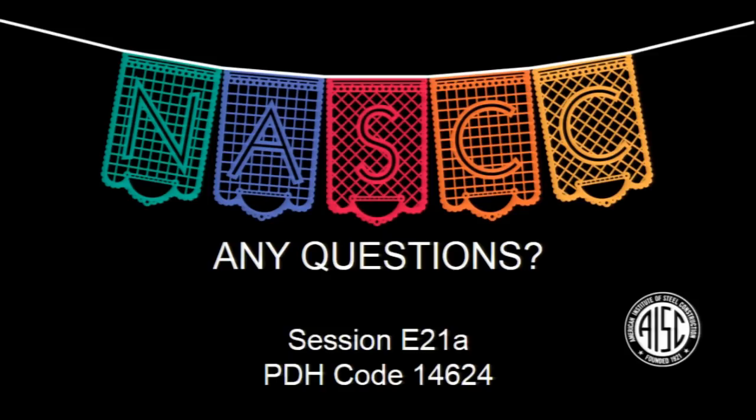First, you're going to start with a Cb of 1 and say, am I okay? Yeah, we had a case where that wasn't okay. So then I start to say, okay, now you can come up with a reasonable, rational method of calculating a C sub B for your type of condition and looking at these other methods that are in the commentary. I think that's what you put on your calculation and it gets reviewed. And if it's rational and reasonable, I think it would be fine. Okay, you have some limits. As long as you're not assuming.